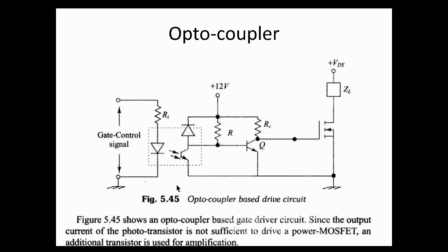I don't know, maybe some of you are doing projects. You will find this kind of circuitry to be useful, in particular when you're using your microcontroller. I know most projects seem to incorporate the use of a microcontroller. So here you could have a signal coming from your microcontroller and you connect this directly to your opto-isolator that you have selected.